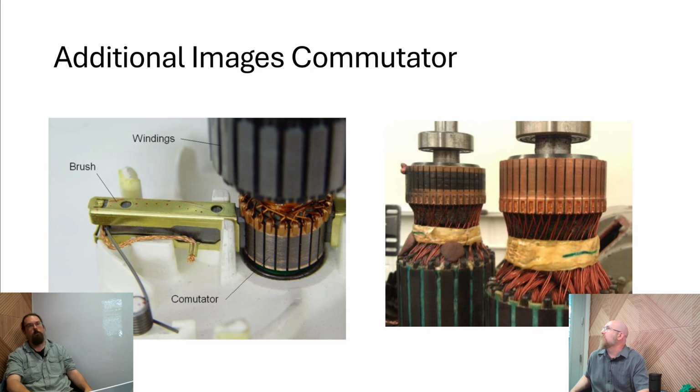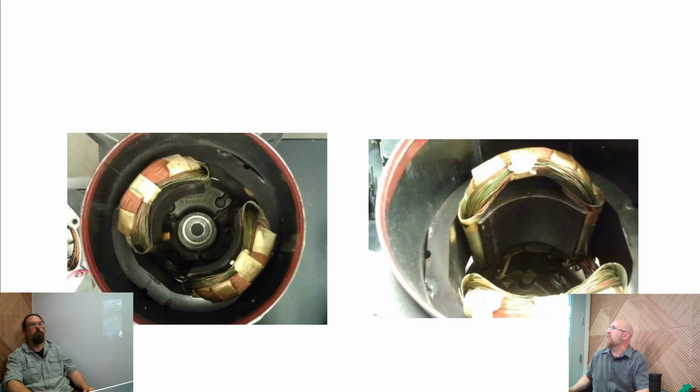Essentially we have a bunch of field coils that we are going to energize in sequence, and their polarity is going to shift based on their relative positions to the two brushes, because one brush is positively charged and the other one is negatively charged. Depending on which orientation it's in, we're getting different polarities out of the fields in relation to the stator fields, which we will cover a little bit later.